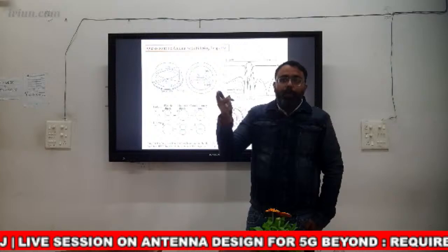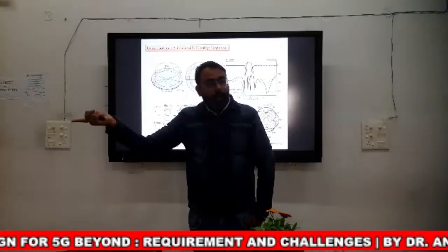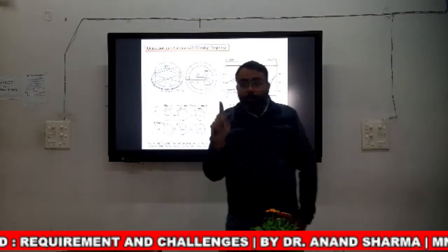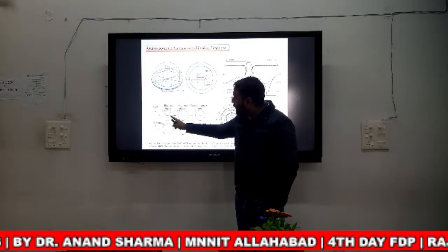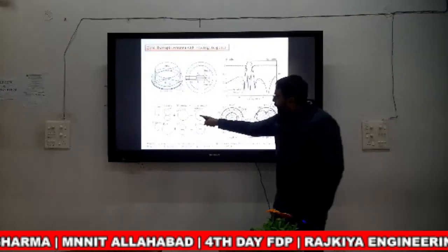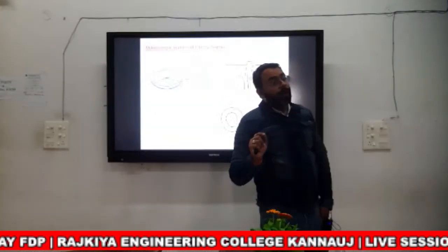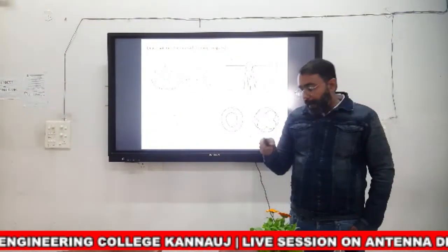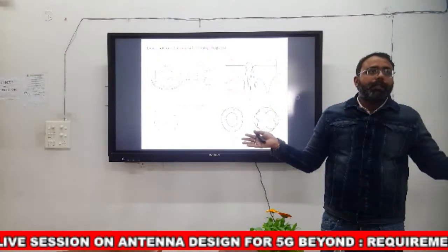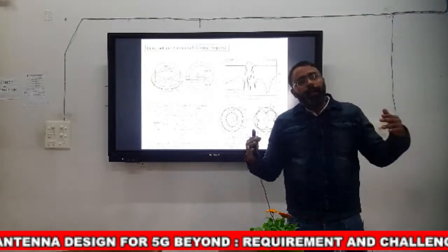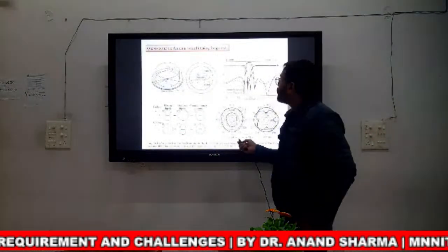Similarly, a magnetic dipole has an omnidirectional radiation pattern in the E plane and an eight-shape pattern in the H plane, just the reverse. If your radiator behaves like an electric and magnetic dipole at the same frequency, then you get a radiation pattern omnidirectional in both planes, E plane and H plane, and that is called a quasi-isotropic radiation pattern. It can be used in place of a circularly polarized antenna. Okay. Thank you so much.